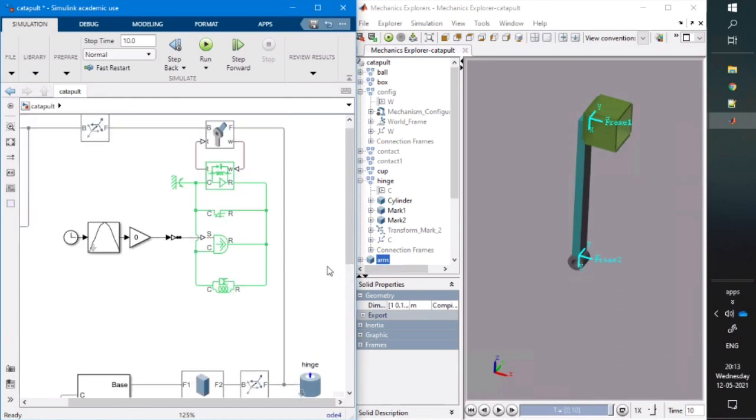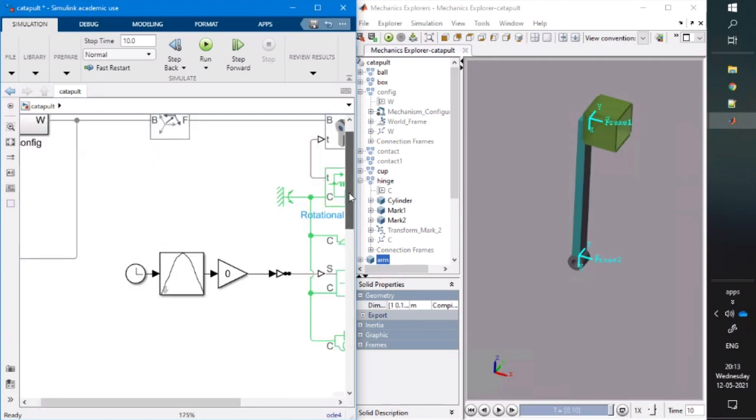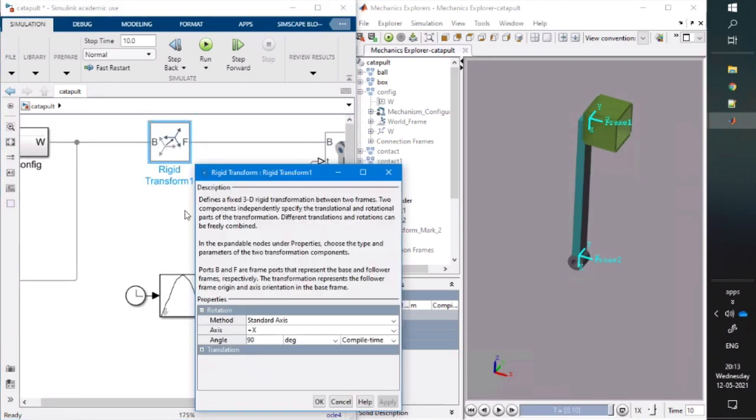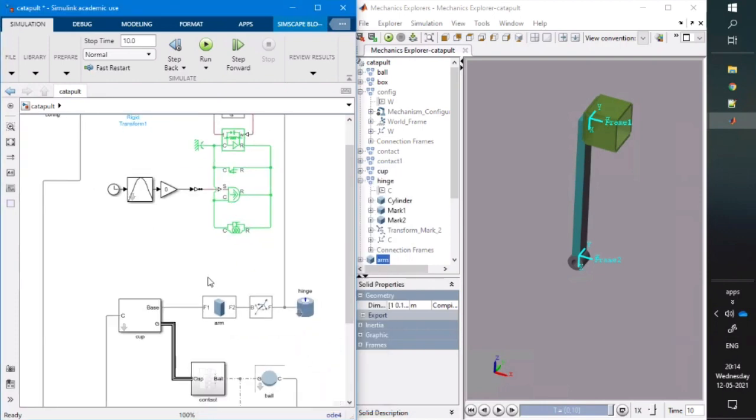Yeah. So MATLAB and Simulink, again, is very good at managing variables. So any of the blocks you touch, you can use MATLAB variables directly. So you have rigid block here. This I can put as a variable. So maybe this is some variable I have defined in workspace. I can just put it up here. It will take it up. So similarly, all of these are directly customizable.